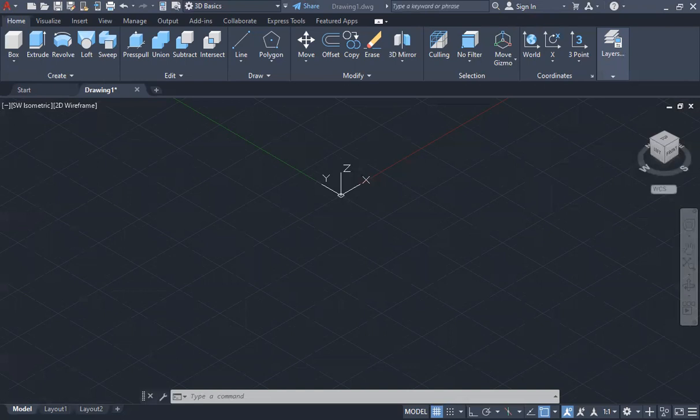I'll break it down into, and then I'll draw this all as one shape, one big L, and then extrude it to a distance of 38. 38 comes from the radius of this semicircular section here, so the diameter would be 38. That's why we're extruding to a distance of 38. What I'm going to draw first is this L section. So it'll be 125 by 64 by 25 by 54 by 100 by 10. All these dimensions are taken from this drawing.